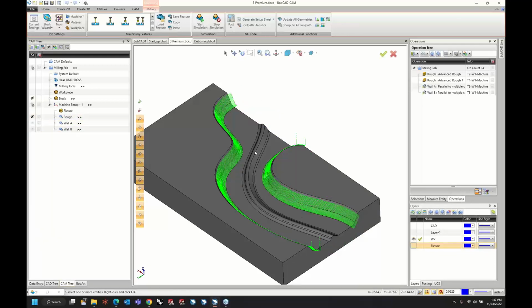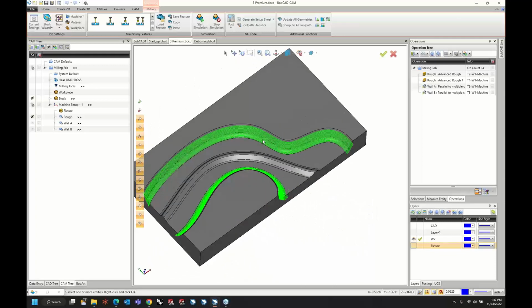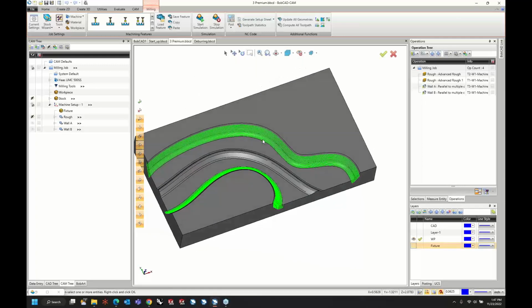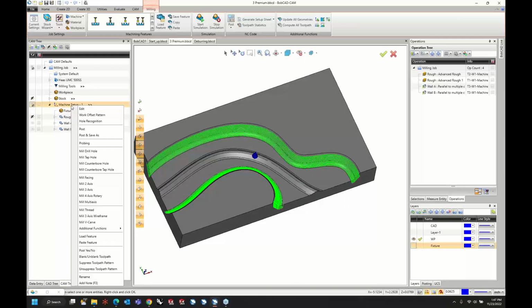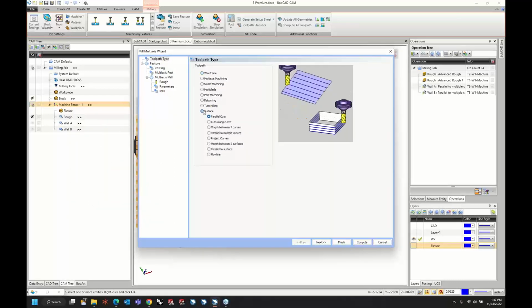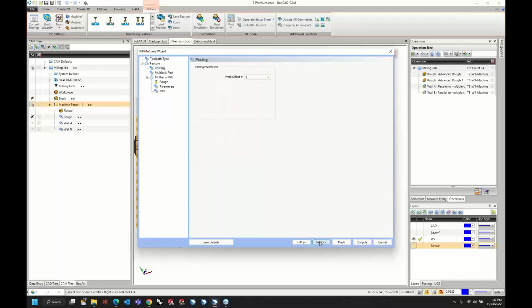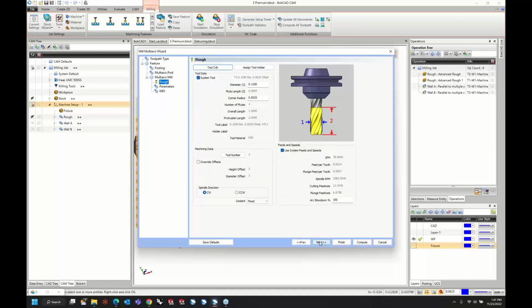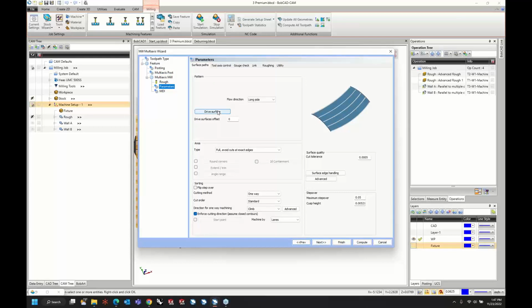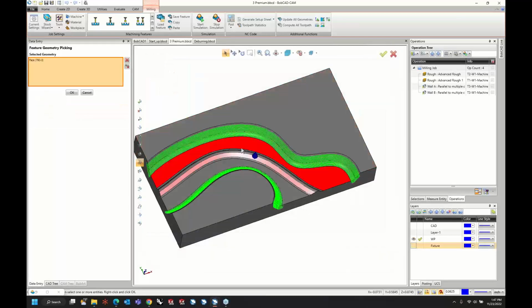Now, the floor down the middle, one of the toolpaths that I do want to show you guys, that I didn't really plan on using, but I want to use it anyways. It's one of these surface paths, and it's called Flowline. Flowline is a really good toolpath for just a quick and easy, smooth, surface-driven path. You really don't have to set much. It's just a drive surface. So I'm just going to pick this surface here.